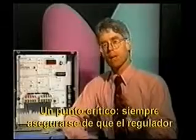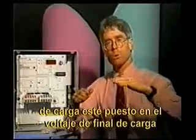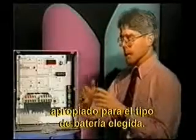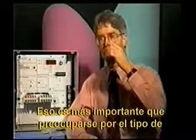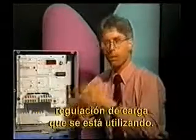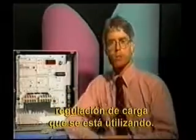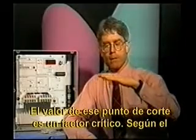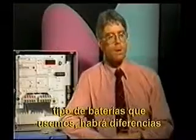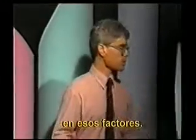One critical point: you've always got to make sure that the charge regulator is set to the proper end of charge voltage for the kind of battery you're going to choose. It's really important. I think it's even more important to have the proper set point than worrying about which type of charge regulation you're using: pulse width modulation, series type, shunt type, and so on. The value of that cutoff point, the point at which you take your batteries to be charged, is a critical factor. We have differences in those factors depending on the type of battery that we're going to use.